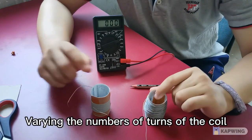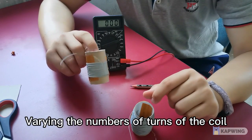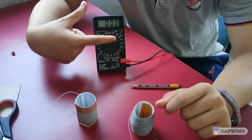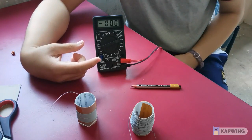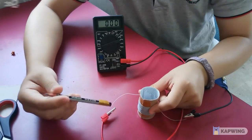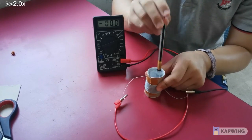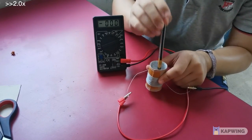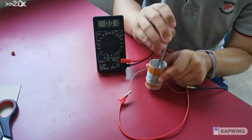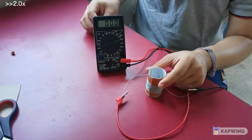And here I have made my coil. This is the coil made out of 200 turns, and this is the coil that has 30 turns, and this is the multimeter set to 2000 microamps ammeter. Okay, as I put this in, we can sense some current flow. There is some current induced in the coil. It has a maximum of 5 microamps.